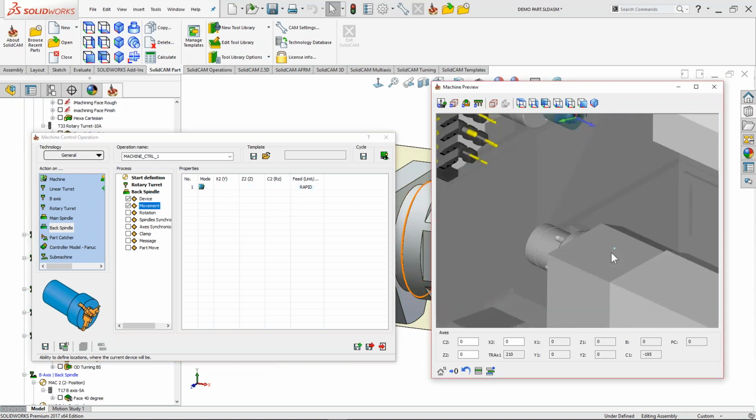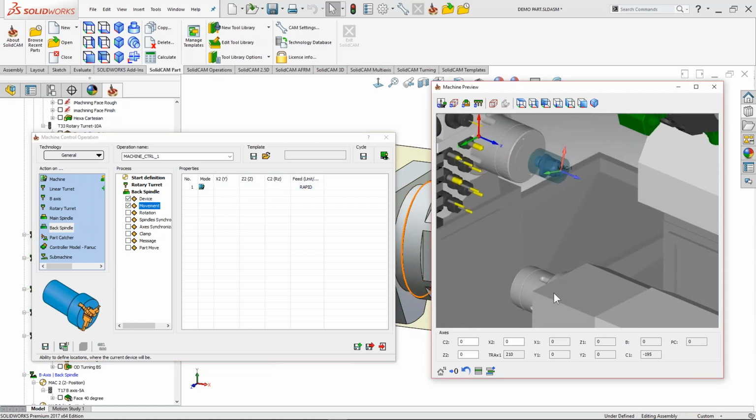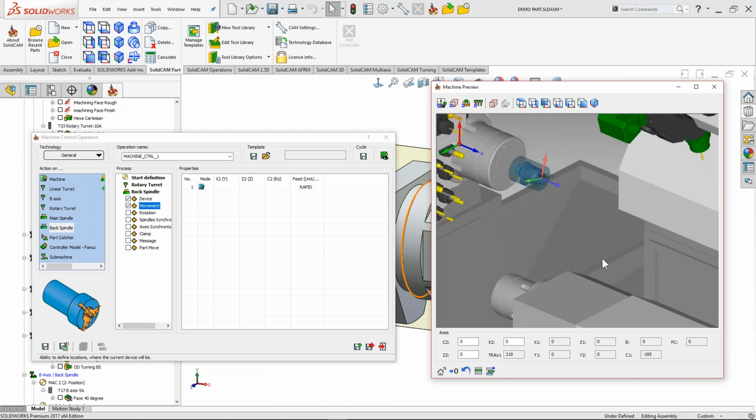And as you note, this machine has the X2 axis, which, before I make the part transfer, I'll need to position in the part transfer position. For this machine, it is constant, it is 469.